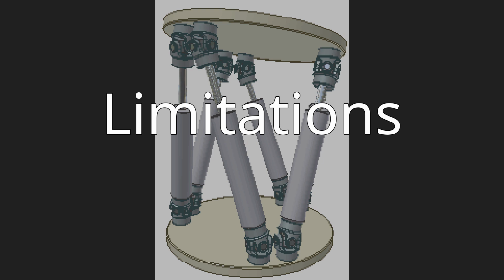The filters themselves may also introduce false cues, defined as: 1, a motion cue in the simulator that is in the opposite direction to that in the aircraft; 2, a motion cue in the simulator when none was expected in the aircraft; and 3, a relatively high frequency distortion of a sustained cue in the simulator for an expected sustained cue in the aircraft. The previous definition groups together all of the cueing errors that lead to very large decreases in perceived motion fidelity.